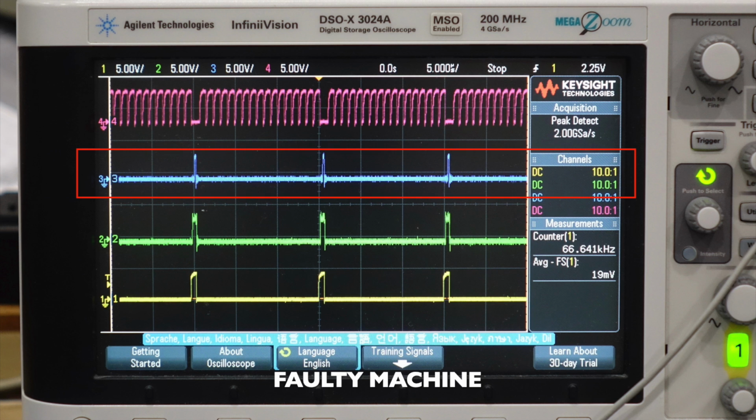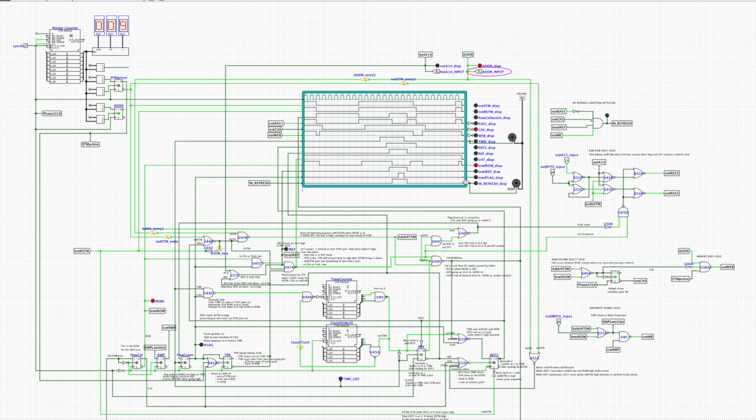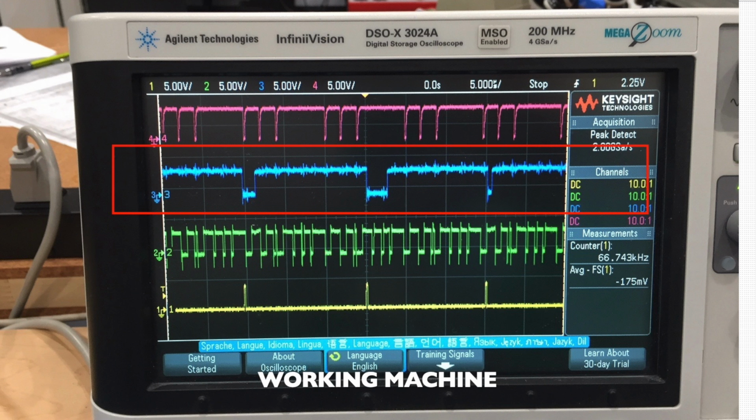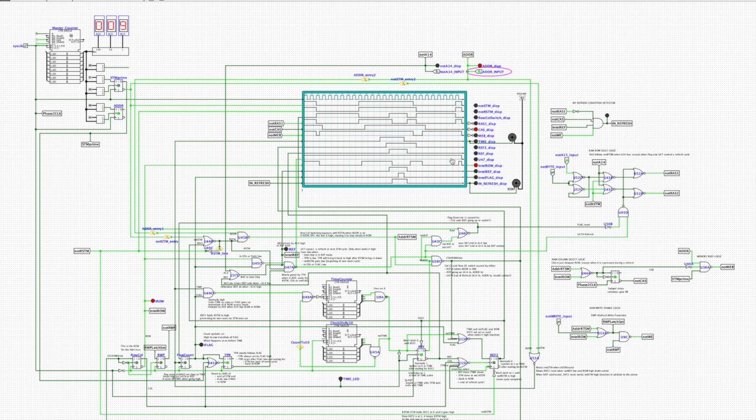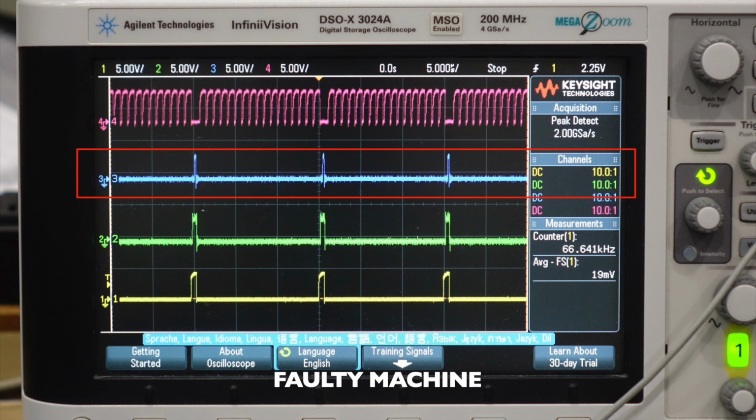Since on the good machine and the bad machine, the processor is not executing the same instructions because one boots, one doesn't. One was stuck in ROM and was doing the refreshes one way, basically where we had the count mostly high and coming down from time to time. And the other one was stuck in memory somewhere and was doing this refresh where the count is low most of the time and goes up in very short bursts.